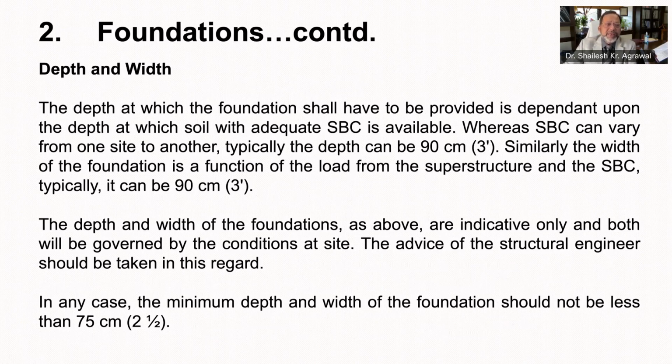In any case, minimum depth and width of foundation should not be less than 75 centimeter or 2.5 feet. These figures which are given to you are just indicative and governed by conditions at site. Advice of structural engineer is highly recommended as cost-effective design can save a lot of money in foundations.